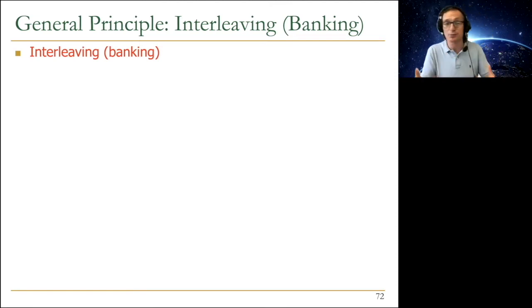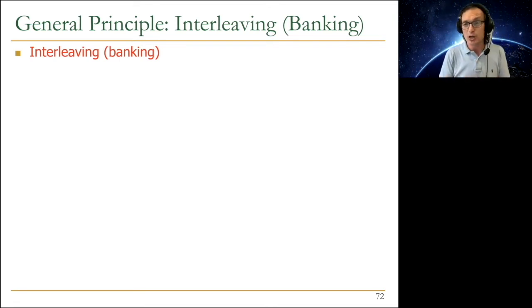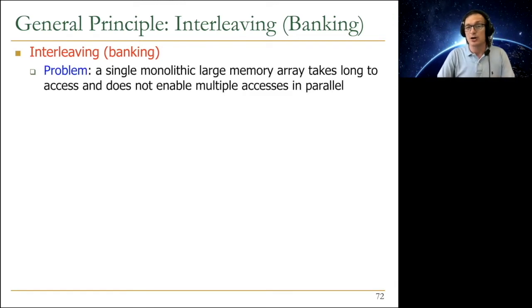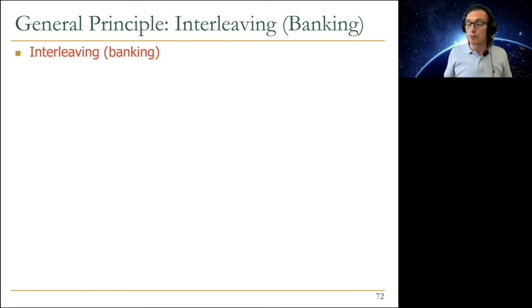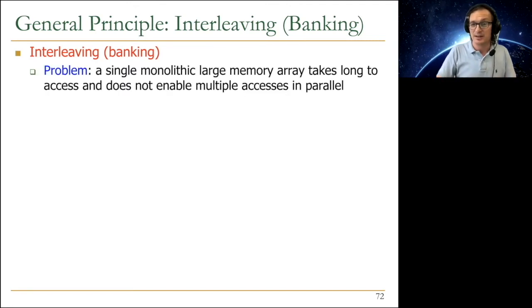We want high throughput, 1 word per cycle in a vector processor. In a GPU, we want even more. So why don't we bank the memory such that we can start one access per cycle in each bank concurrently? There our goal was to get one word per cycle throughput. So banking certainly helps throughput as well. But it also helps this. Well, this actually has throughput in it as well.